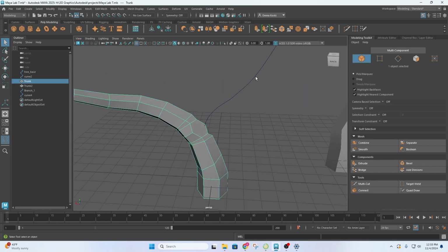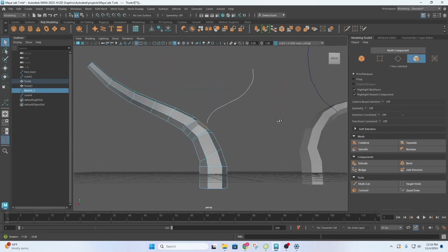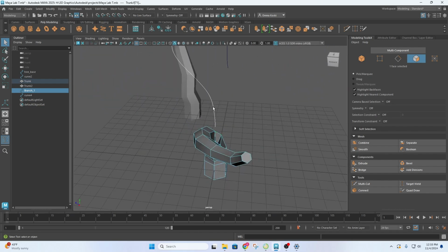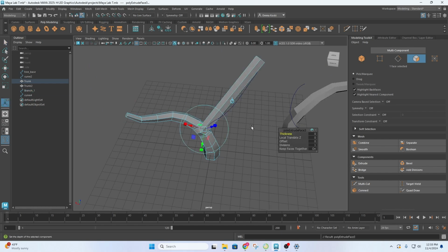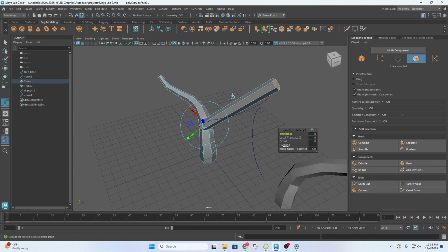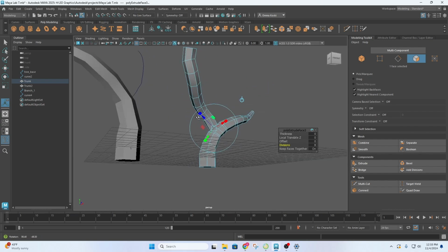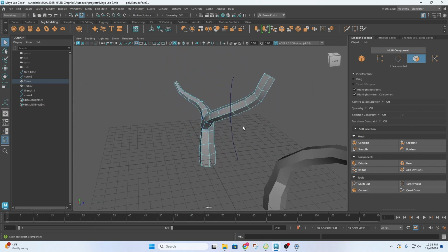And we're going to do the same thing. Object mode, select the branch curve. And then right-click menu, face selection over your tree again. So now all I have selected is that one face and my branch curve. And then I'm going to do the same thing. Control E to extrude. Right? So we extruded it out. And then increase the number of divisions so it follows the curvature of your branch. Awesome. Something like that. Hit hotkey Q when you're happy with it.